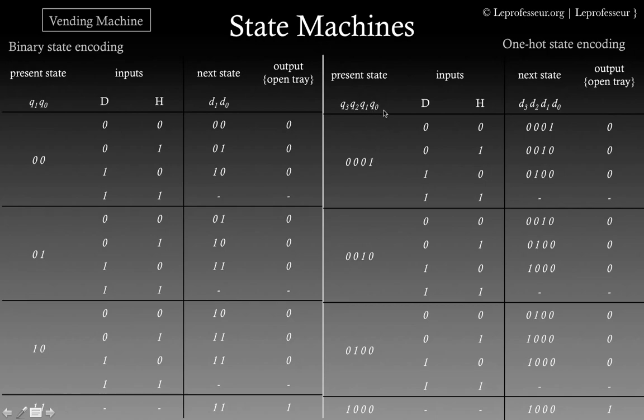If the machine is in the Q1 state, the Q1 bit is set. If it is all 0 0 0, you may think of it as a reset state. So one hot encoding is fairly simple. Say we have 4 states and 4 flip-flops, and each bit that is set represents each state.